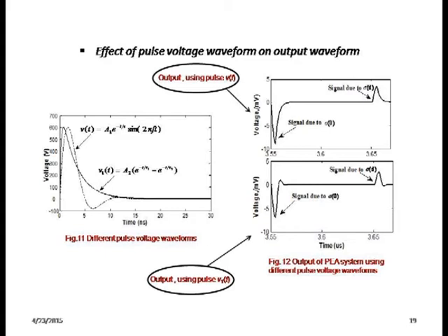So this is smooth, and due to this one this type of waveform is obtained. It doesn't mean that this is actually the space charge; it happened due to your probing pulse. So the sharpness and the shape of the probing pulse is also very important in estimating the space charge, right.